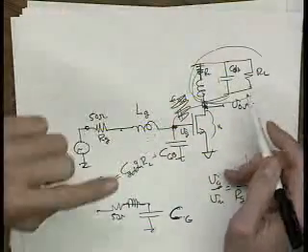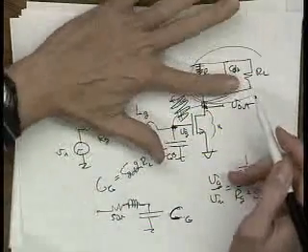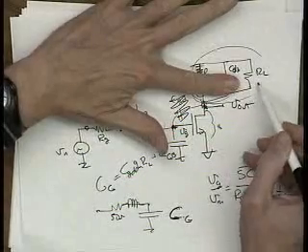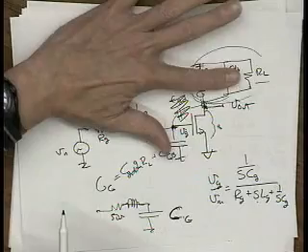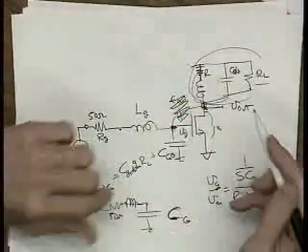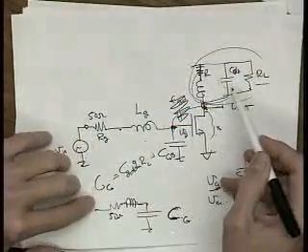In other words, at the tuned frequency, this too becomes infinite impedance, and all you see left is the RL. And that's what you'll find in your homework. So inductors are really pretty neat. Now, they're about the same area as capacitors, and I mentioned that last to you.